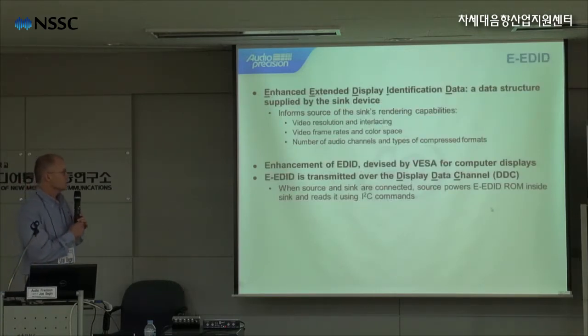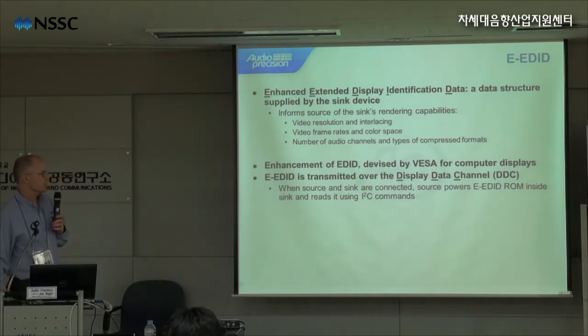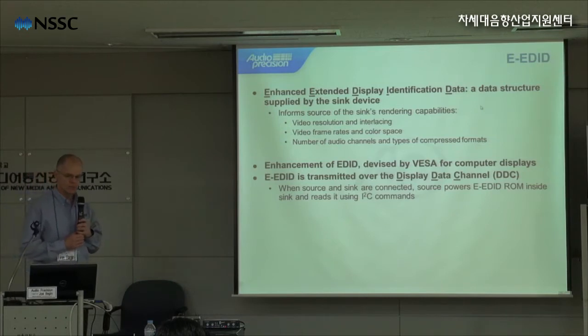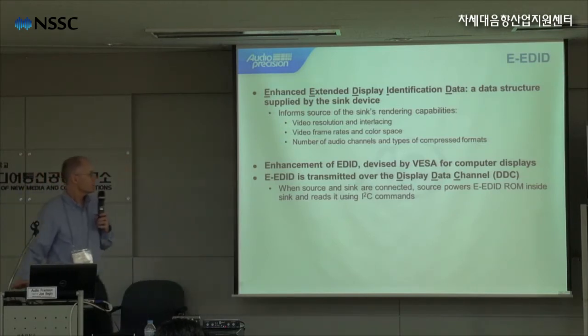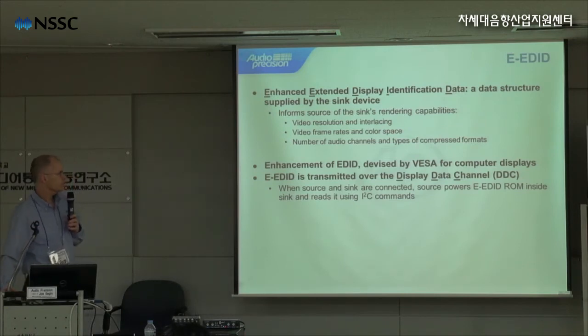There's also the concept of EDID, which stands for Extended Display Identification Data, a data structure supplied by the sink device. So when you connect a series of HDMI devices together, the end sink device informs the source of its rendering capabilities.